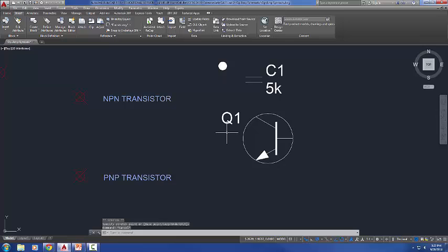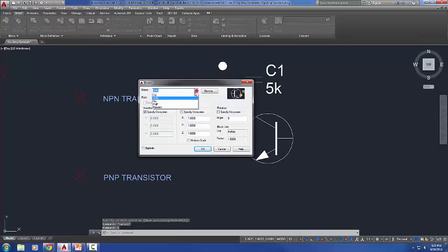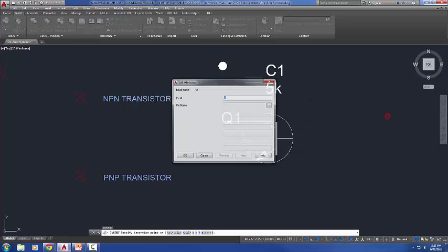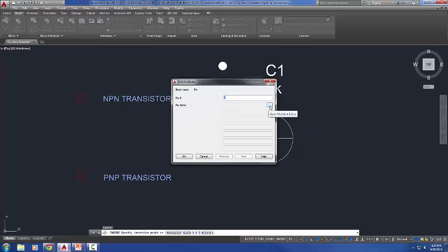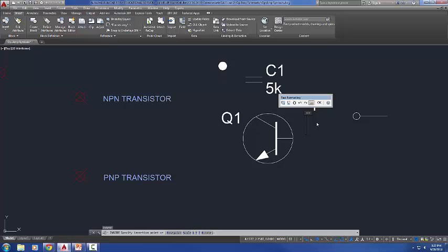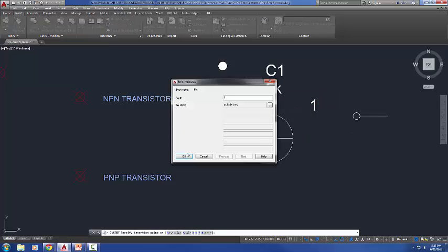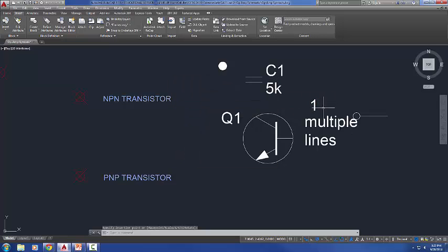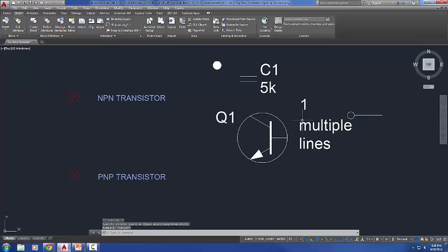At the beginning of this project, we turned our UCS follow on so that our screen could rotate when we created a new UCS. If I forget to turn it off, then at the end, when I try to set my east elevation current, you can see here it's going to kind of zoom into that east elevation, the boundary lines that I set, and it's going to pop back out. I don't know if you saw it happen that fast, but now I've got that east elevation, and I can move the text out of the way. If I set my UCS follow back to 0, it doesn't zoom into that boundary.